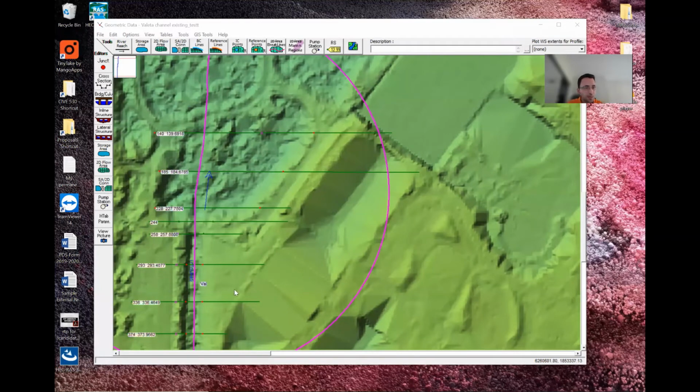Okay, so we have everything ready for us to add a road deck here and add a culvert underneath. So our river system is connected. Let's do that. First step is finding the closest cross section that you have. So we have 258. Our road deck is like 3-4 feet downstream of it.